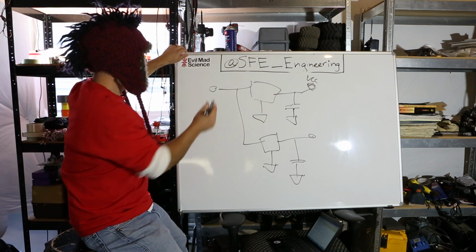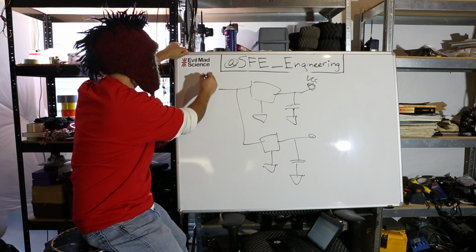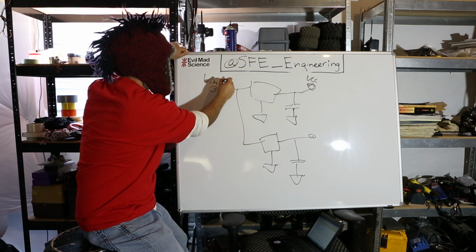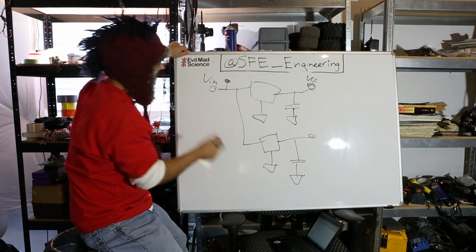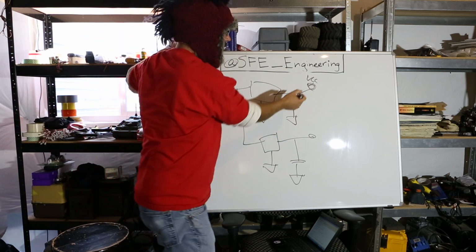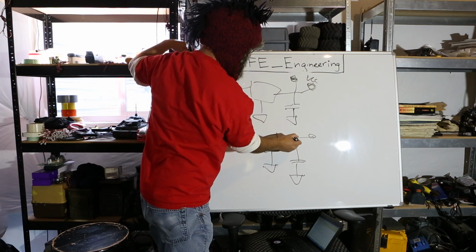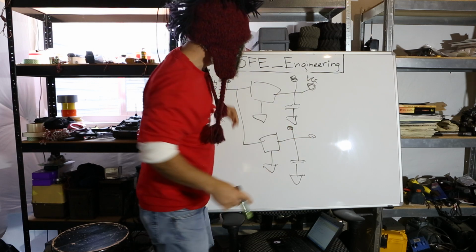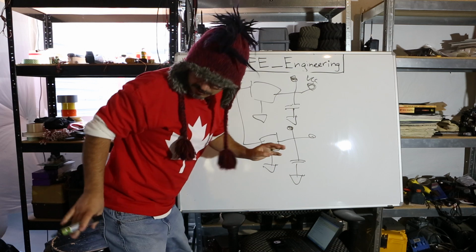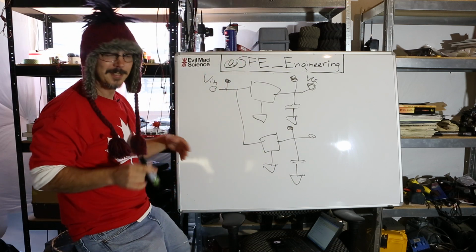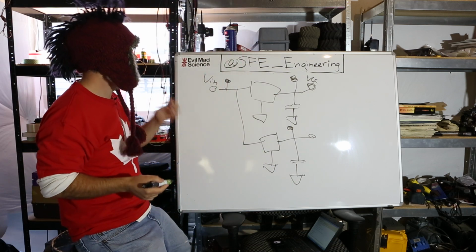And you're going to want to know all of those. First of all, you want to know V in, so you're going to want a test point there. And you're going to want to know what your VCC is. You want a test point there. You want a test point here on this other regulated voltage. All your regulated voltages, you're going to want to know right up front to tell you what your circuit is doing, first and foremost.